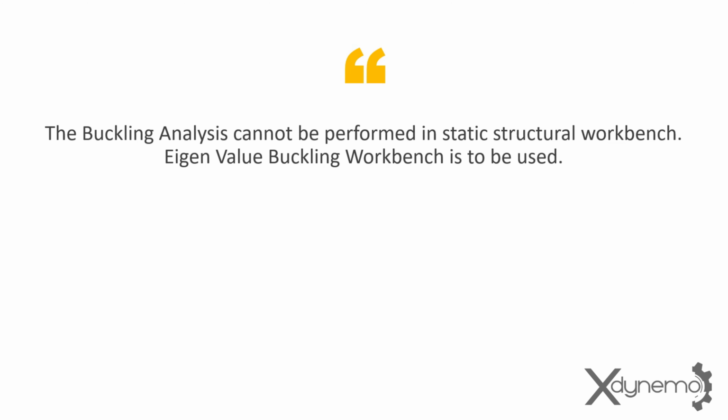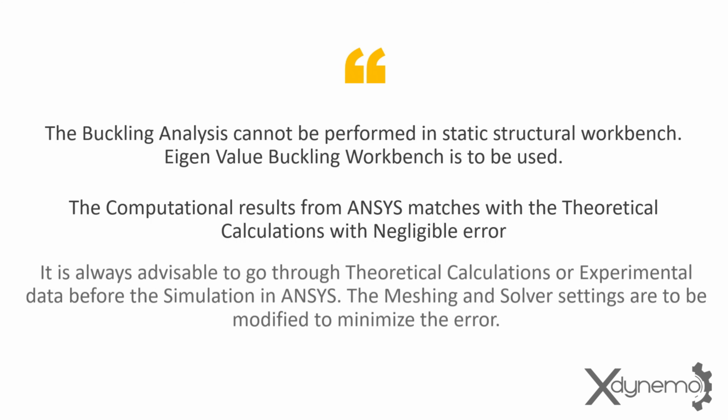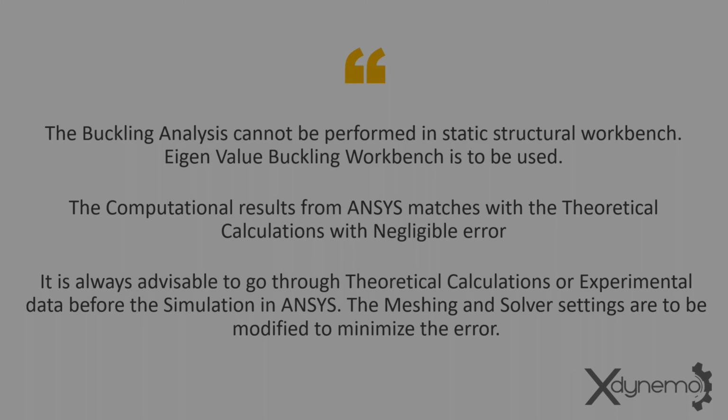Here are the conclusions we get from this analysis. The buckling analysis cannot be performed in the Static Structural workbench. Eigenvalue Buckling workbench is to be used. The computational results from Ansys match the theoretical calculations with negligible error. It is always advisable to go through theoretical calculations or experimental data before the simulation in Ansys. The meshing and solver settings are to be modified to minimize the error.